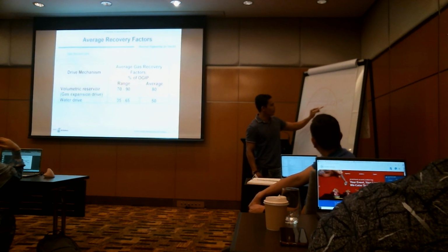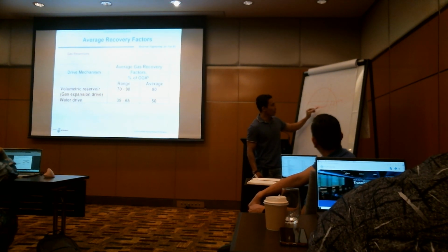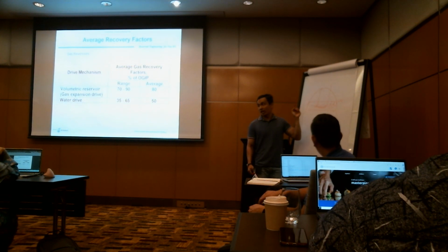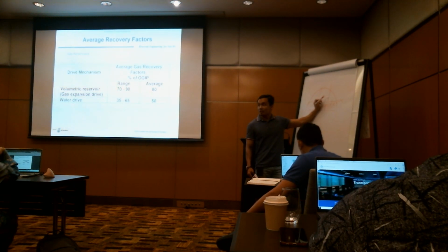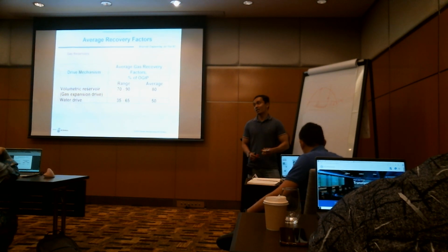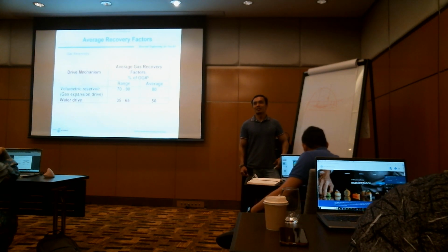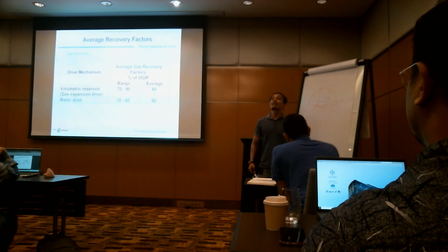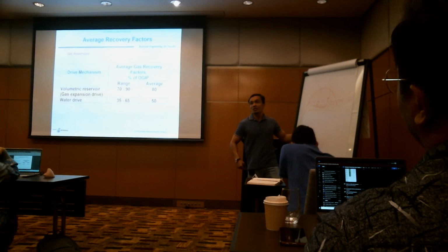So you are limited to this only. Towards the end, the oil column is very small, very thin already, so you are left with a very big gas cap. At that time you will maybe add perforations here and produce the gas only, and we call it the gas cap blowdown. That will be the last. And you may have to convert, maybe as a top-up facility for gas demand. For example, you have a shortage of gas and you want to produce.